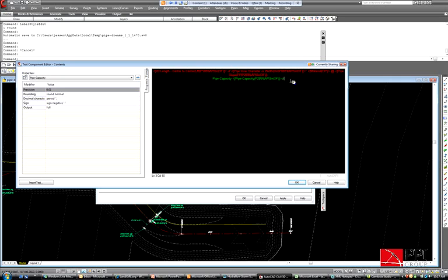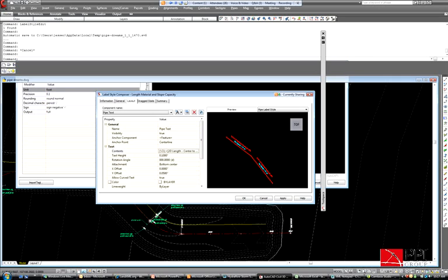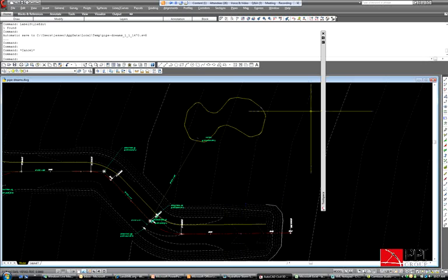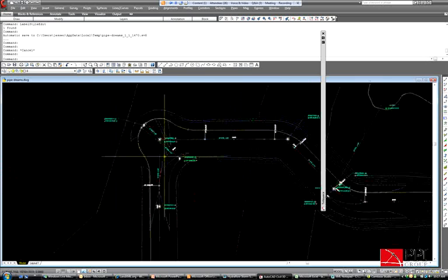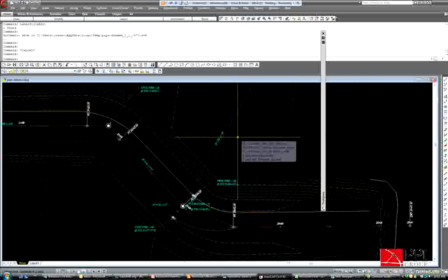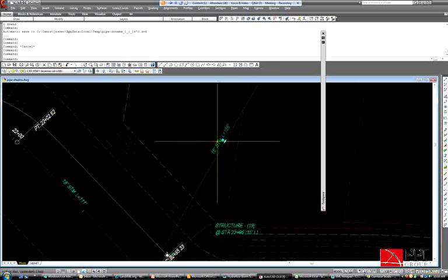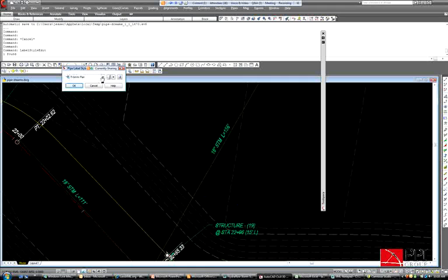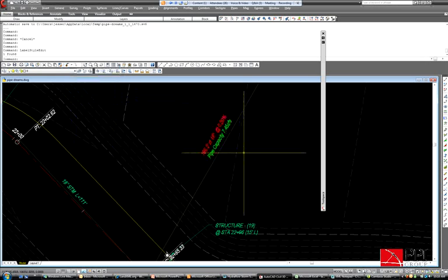Units over here on this end, because those typically won't come in. You add them manually. So that's how that one got in there. And then similarly, now that I've got that label style in here, I can come in any of these pipes. I guess the alpha pipe would be the most logical one to bring this into. Right click on that and go edit label style. And now I've got my length, material, and slope with capacity as a style in there.